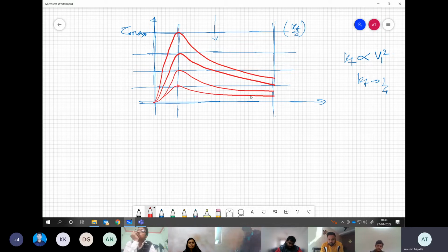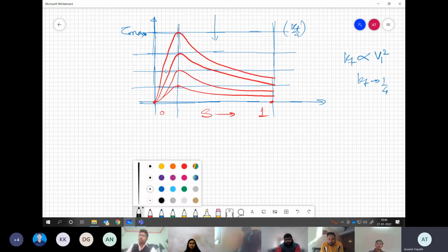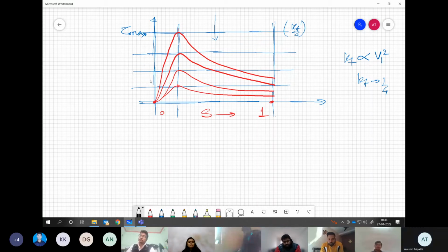Now this kind of starting is okay if we have a fan load to start. Fan load means at the starting the load torque will be 0. Correct, sorry, here at the starting, which means S equal to 1, the load torque will be 0 and it will only increase with omega. So if I draw with black, the characteristic for a fan load may look like something like this. It may not be significant even for a few RPM of the motor operation.